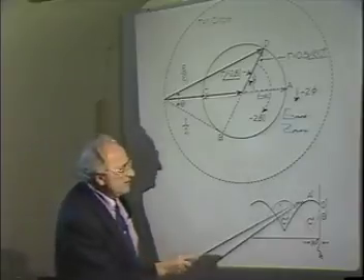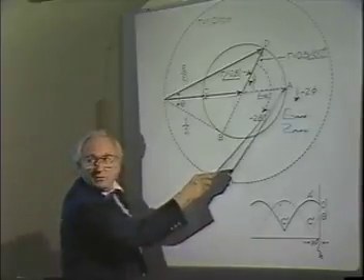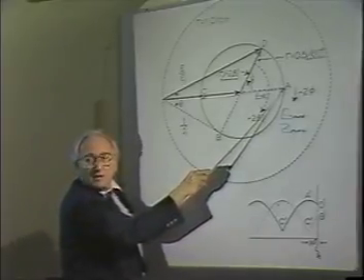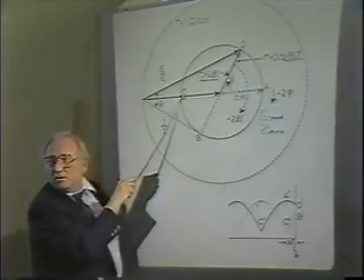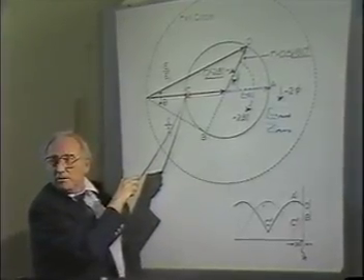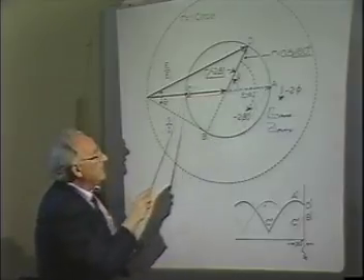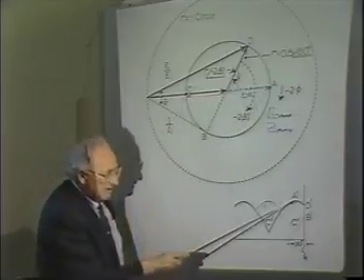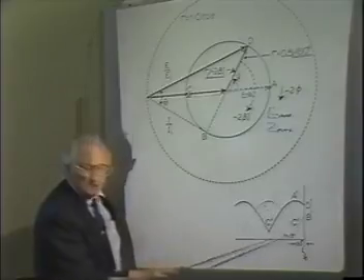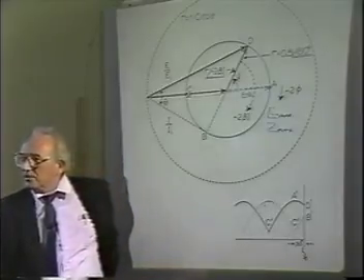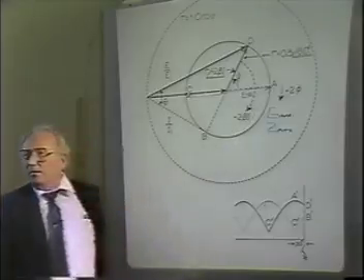See, if here's Z max, if I tell you Z max is 150 ohms, you know the reciprocal of that would give you admittance over here, wouldn't it? 1 over 150 ohms is over here. So on the chart, maximum impedance and minimum here would mean this point right here on the transmission line. But if I want both values, I have to go 1 over here and 1 over here.